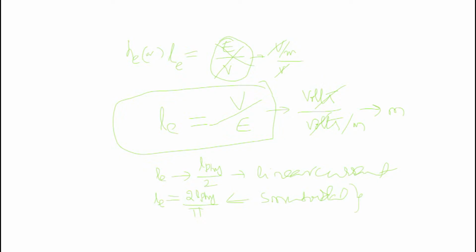This sinusoidal current distribution is observed for the quarter wave monopole antenna and half wave dipole antennas. Quarter wave monopole antenna means lambda by 4 antenna; the length of the antenna is lambda by 4. And when length is equal to half of the wavelength, this one is known as the half wave dipole antenna. So these are the different wire antennas: one is quarter wave monopole antenna, and another one is half wave dipole antenna.